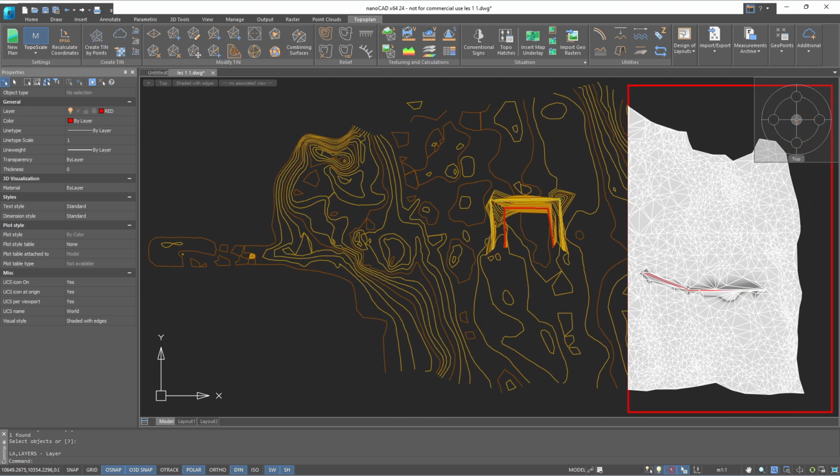Continuing to work with the terrain, let's add labels and BERGSTRICHes to the contours. Before launching the commands for generating labels and BERGSTRICHes, it is necessary to determine the scale of the final drawing. We will prepare the topographic base at a scale of 1/1000. Set the required scale by selecting the desired value in the Toposcale drop-down menu.